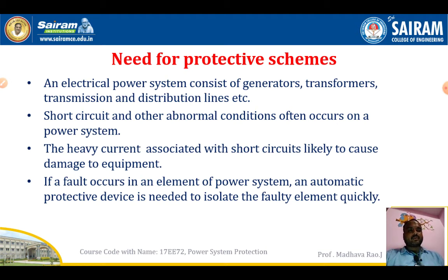Current transformer, what will it do? It will sense the high current. Voltage transformer, what will it do? It will sense the high voltages. And also protective relays. These are the devices we use to isolate the faulty section of the power system from healthy sections. Generally in heavy voltage or high rating applications, we will use circuit breakers. In further modules, you are going to study different types of circuit breakers and different types of relays.